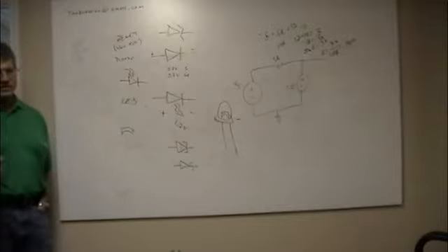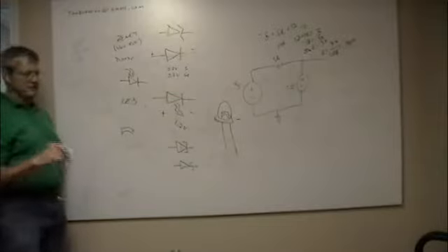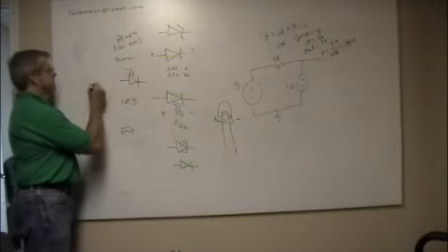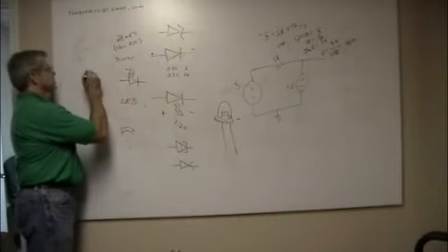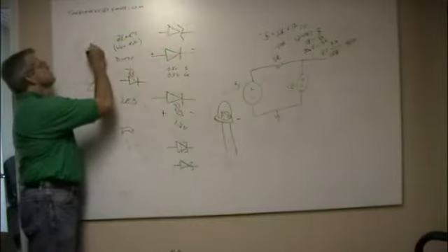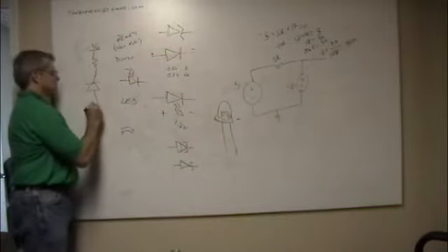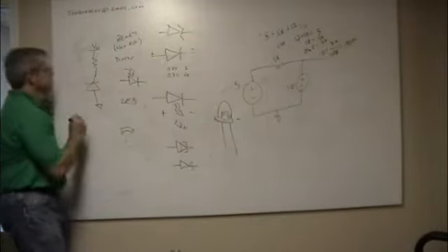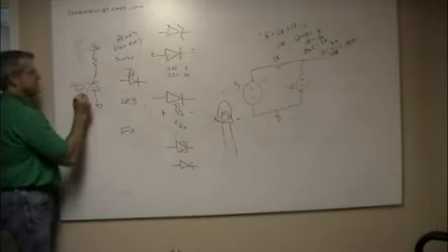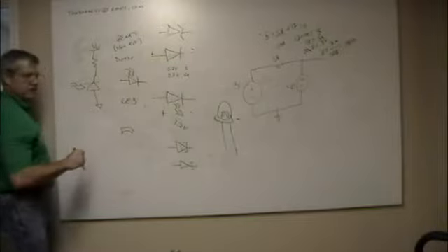Different things going on. In the end, the result's sort of the same. But you hook a photodiode up backwards, again to a ballast, usually to some voltage, to ground. And when light hits it, it breaks over and conducts.